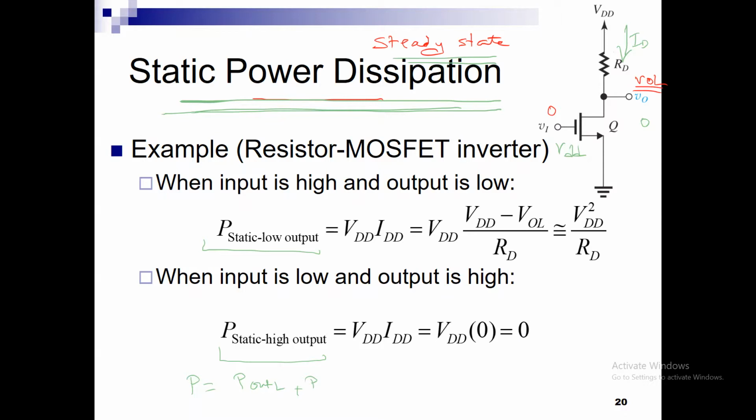We have 50% of the time in this state, and another 50% of the time we are in the other steady state. If it is unbalanced, then we multiply it by the weights. Let's say that the output is low 30% of the time, then we put that weight into our average, instead of here where we are reflecting 50% in each of the two states.